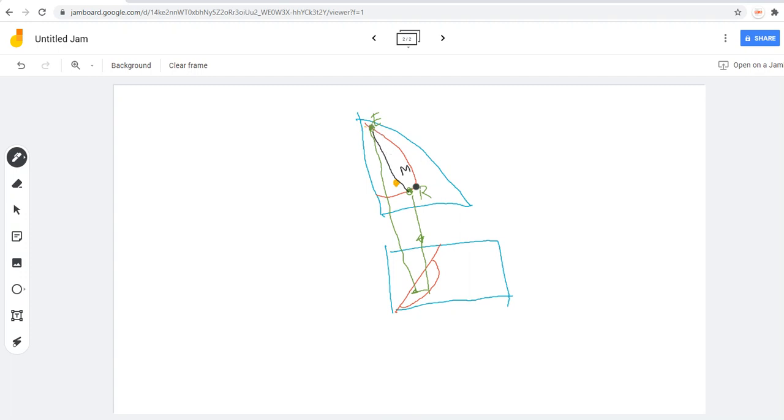What you're going to do is read the A here and read the C here. That would be the composition of your raffinate layer. For the extract layer, you read the A here and you read the C here. That would be the composition of your extract layer. For you to know B, all you have to do is get the sum of the A and the C and then subtract it from 1. That would give you the B.